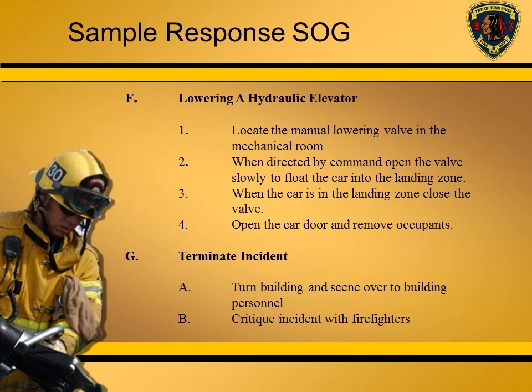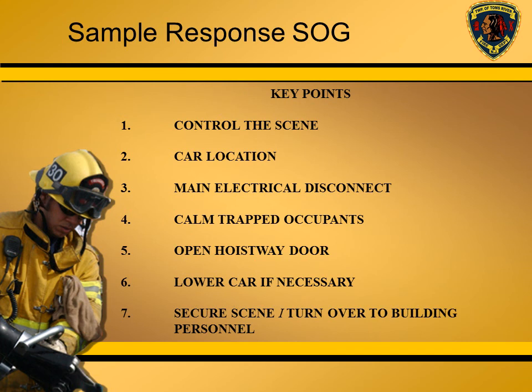To terminate the incident, turn the scene back over to the building personnel. Request that they have an elevator technician respond and critique the incident with firefighters. Some key points: control the scene, locate the car, always disconnect the power to the car, calm the trapped occupants, use the proper keys to open the hoistway door, lower the car if necessary, and secure the scene and turn it over to the building personnel.